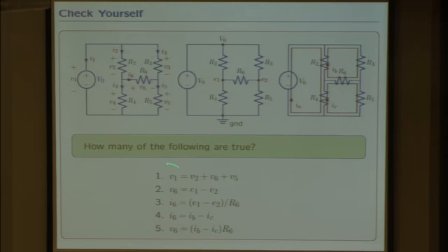This first equation, what is this? Give that a name. KVL. Is it correct? Sure. You need to figure out which path it corresponds to. The only V's are over here, right? So therefore, it must be something that has to do with this circuit. So this says that there's 1, 2, 6, and 5. That's path 1, 2, 6, and 5. So all you really need to do is check the polarities.